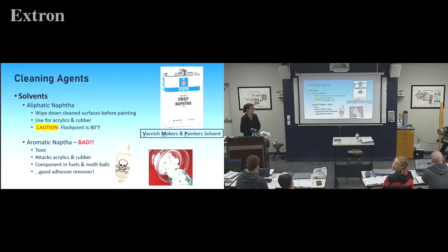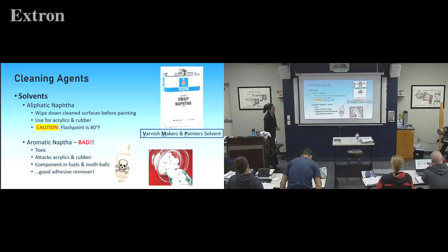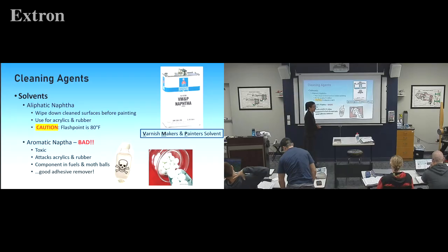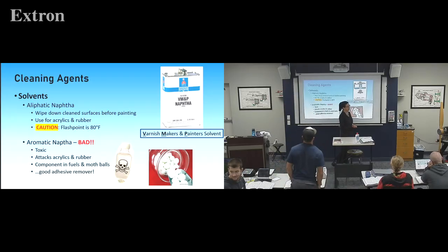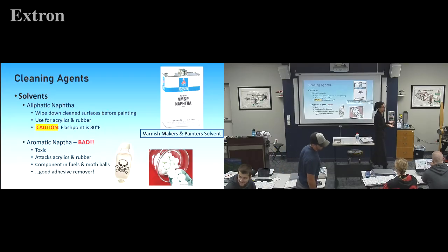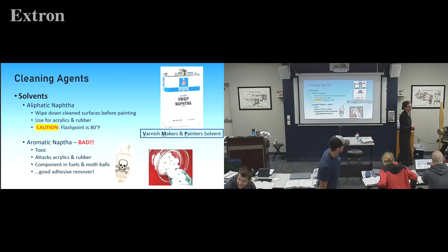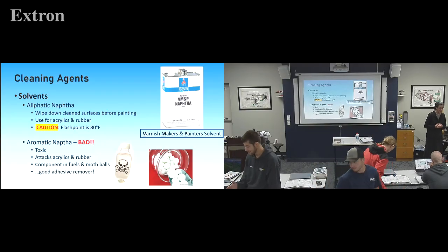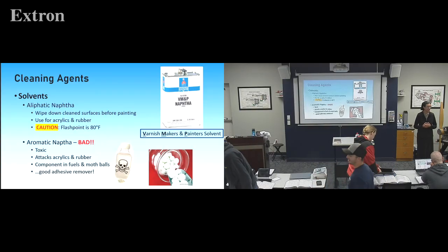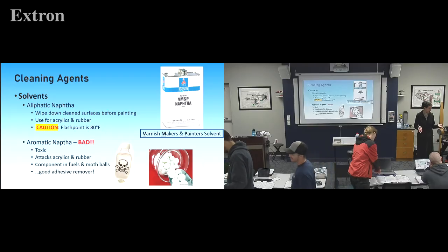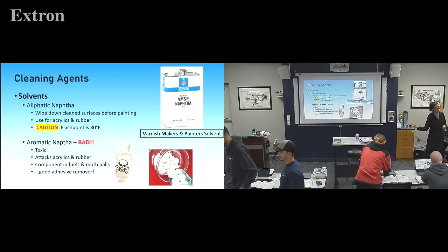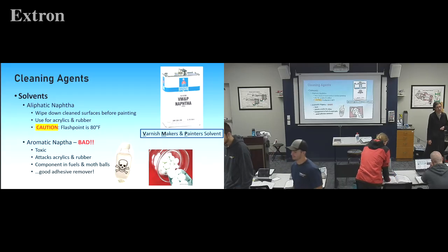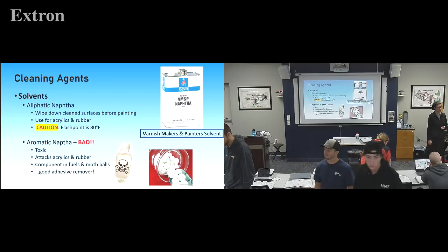So aromatic is always bad, because it attacks stuff. Correct. Can you use it carefully in the right situation? Yes, maybe, in a controlled environment. There's better stuff out there that does just as good of a job. It smells like mothballs. I think in the olden days they used it because there wasn't better stuff to use. So it's still in the textbook, still in AC 43.13. Actually, is it in the new AC 43? I know it's in the textbook.